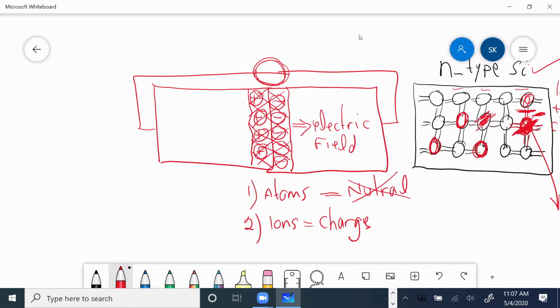So it cannot be measured, but we can detect it. There is an electric field. That electric field exists, and that electric field is enough to prevent these electrons and these holes from traveling any further. This electric field will deter holes that way, will deter electrons that way.